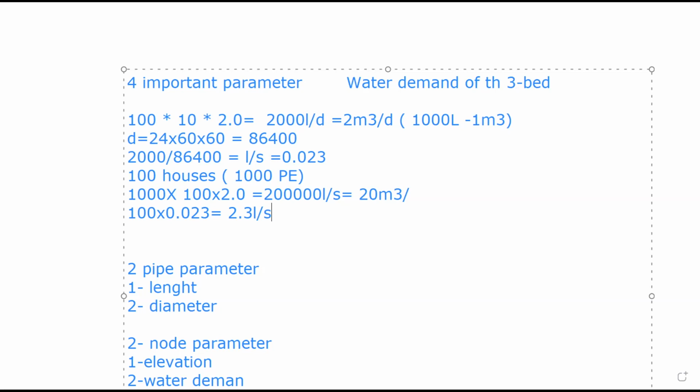And what it also means is that the pipe size must have the capacity to convey this kind of flow. If you cannot convey it, there's a problem. That's why you as a designer, you as a consultant, must calculate this. And then when you get this, which is now your Q, if you remember our engineering, Q is A times V, surface area times velocity. That surface area is now your pipe diameter.